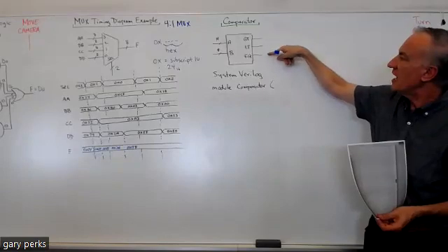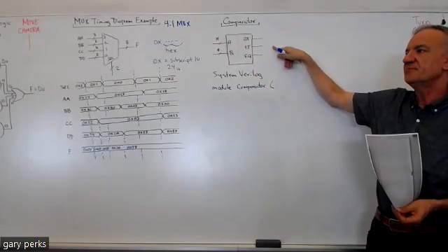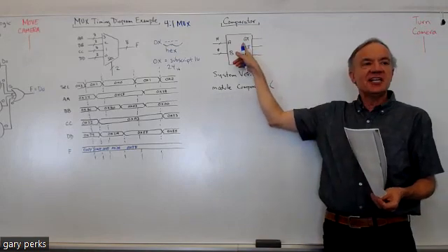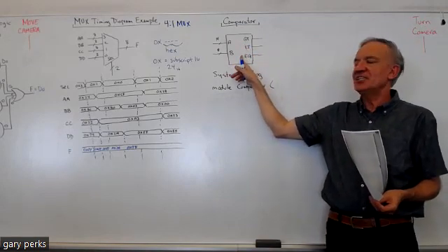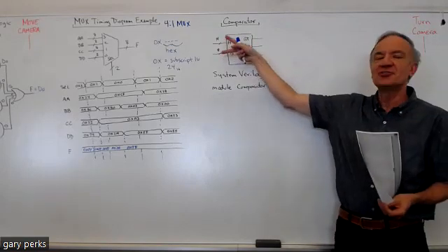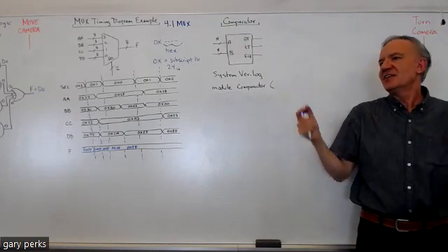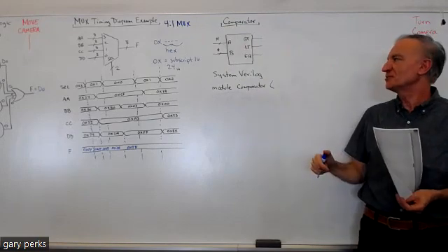Then we've got three outputs, GT, LT, EQ. They're all single bit. Can you take a guess what GT, LT, and EQ stand for, since this is a comparator? A comparator is going to compare these two numbers at the input. So can you guess? Greater than, less than, or equal to.